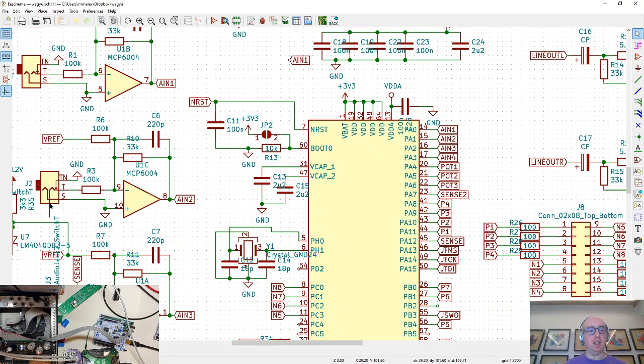The entire circuit for that is here, which is basically a jack, 100K input impedance, a gain of minus 1/3, and an offset from a 5 volt reference, or minus 5 volt reference, I should say, that basically centers it in the output range. So joy. Right, the CV input's done.